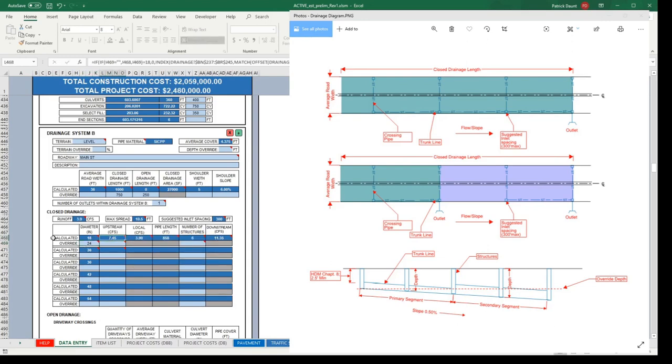Now you'll see that this upstream flow is automatically calculated. So again, this is a 7.45. So this is the maximum flow an 18-inch pipe can see. So 7.45 is injected at the start of this 24-inch pipe, and we can still maintain 858 feet. So the 24-inch pipe can still maintain a full 18-inch pipe plus the local flow, which is basically the proposed area from this 27,000 feet that's coming to this new 24-inch pipe. So we're still pretty good.